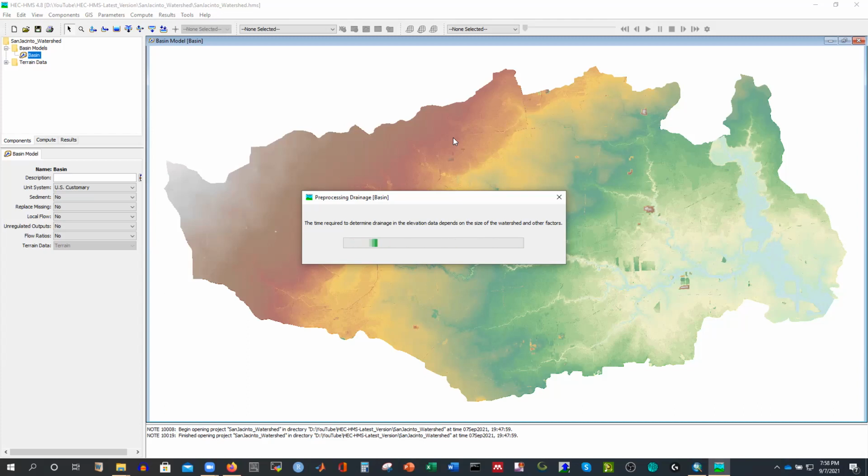So that's why we consider a different reanalysis product. We'll try to use gauge precipitation, because we are not going to use a distributed model here. I'll create the same model as distributed, and I'll do the processing, and I'll show you how to create that gridded precipitation, because it needs some processing, some scripting. I'll show you how to do that, and then you'll be able to run both models, either the lumped model or the distributed model. But you have to follow step by step.